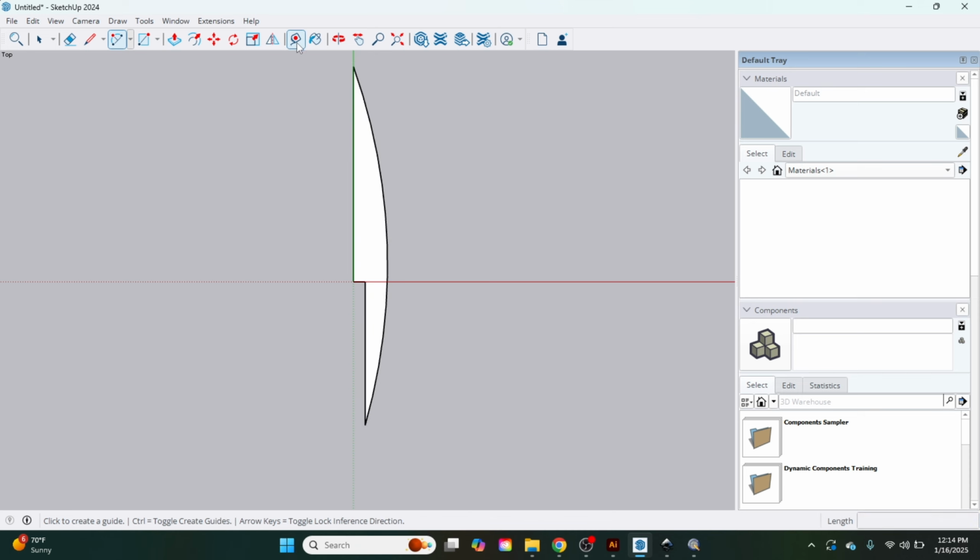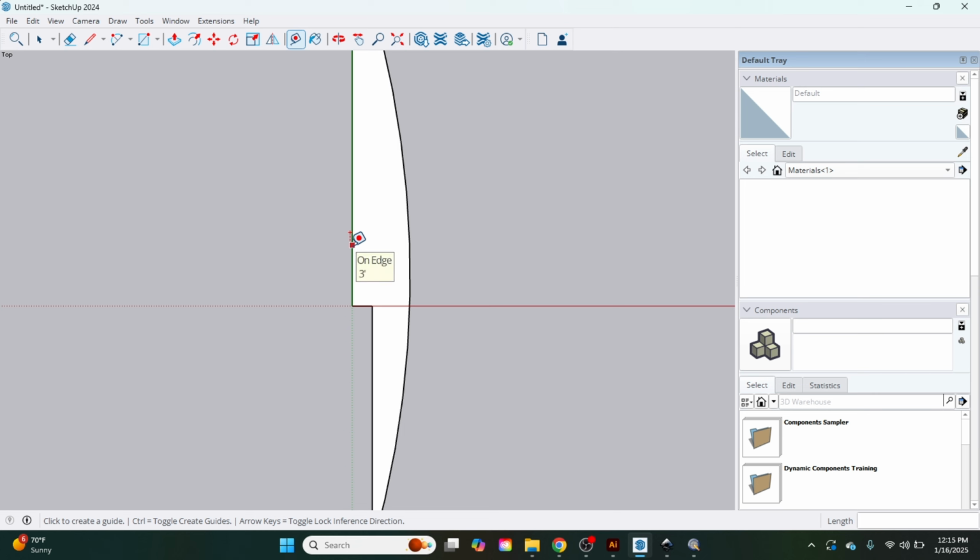Now to verify all this, I want it under 6 inches. So what I'm going to do is go to the end point, and half of this is 30 inches. So I'm going to do 30 inches. See that little mark there? This is the useful process of having a tape measure in the program. So I can go right onto that little tick, and I can go to the very end, and I'm at 5 3/4. So if I'm under 6 inches, that's where I want it to be.